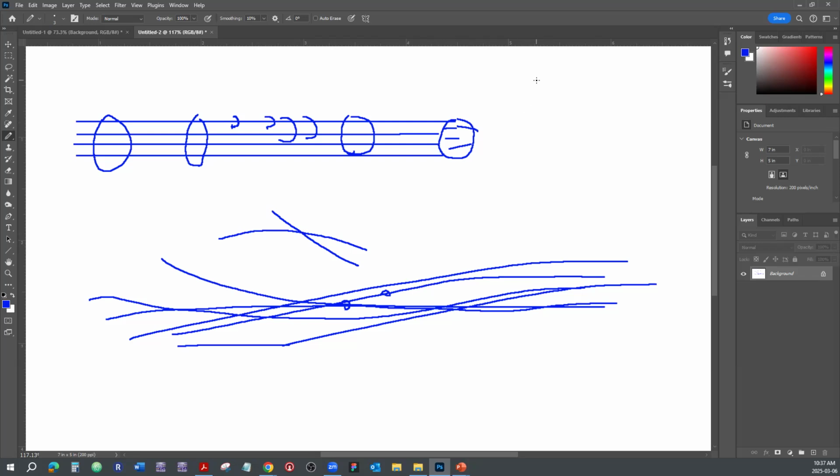Two types of bends usually apply to fiber optics. If you run a cable around the corner of a building, that's a macro bend. If you have a cable sitting in the tray, and you accidentally put something on top of that cable, you're going to create an indentation on it. That's a micro bend.